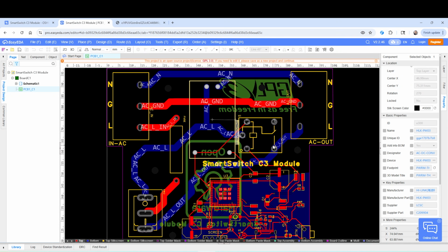Now if we just move a couple of things around on the top layer, we would be able to move this converter module over to the right. We could probably take this relay and move it down, and then that would make enough room for an EMI filter circuit. So now with that little bit of review out of the way, let's take a look at some EMI filter circuit options. We're going to hop onto the whiteboard, and then we'll take a look at a reference design, and we can see a real EMI filter circuit with some part numbers that you can use in one of your designs.